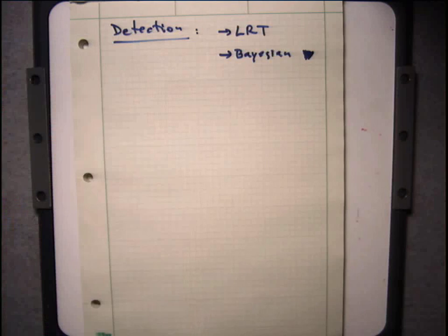You can talk about detection as something that's trying to compare amongst m different hypotheses. Of course, the calculations get more complicated, the bookkeeping gets more complicated, but the bottom line is not that different. So, for instance, let's go back to the 2 hypotheses. When you have 2 hypotheses, the likelihood ratio test divides the space into 2 pieces, right? If your data falls into this piece, you pick H1. If it falls into the other piece, you get H0.